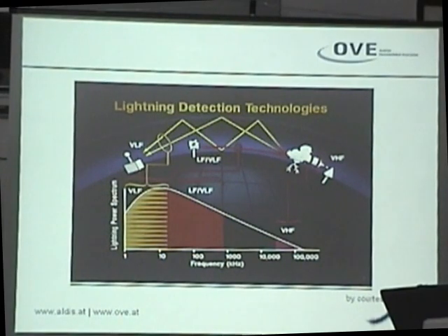They can't distinguish between cloud to ground and cloud to cloud data, they only detect discharges. And a very important difference is that the sensor has to see the discharge. So they need line of sight, because at this frequency the radiation is not bent over an obstacle. So if there is a house or a mountain close to the sensor, it blocks this sensor in a certain direction.